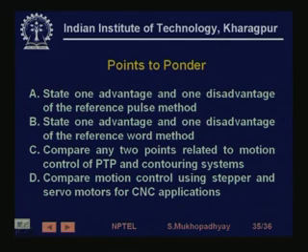And compare any 2 points related to motion control of PTP and contouring systems. So first thing is that in PTP systems, generally motion takes place at no load or constant load, while in contouring systems motion takes place while cutting, so load can vary, and load is generally higher.